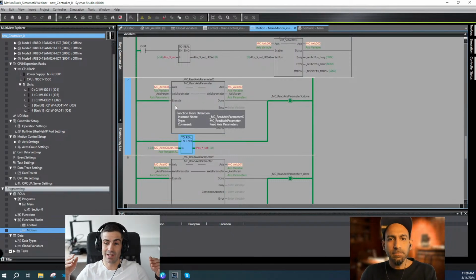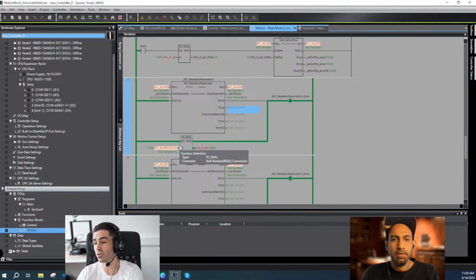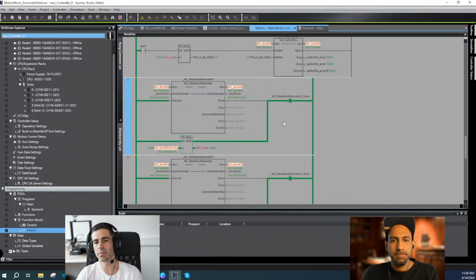Again, we are assuming with this implementation that the virtual version of the axis is generating the trajectory. So we are using the actual position, which is the same as the set point position in the axis, which is the one making the axis move in Simumatik. So we are running in open loop. What we want to investigate is if we can get the set point position instead and send that to Simumatik, and then write back in the virtual axis what we want to be the actual position, not the ideal